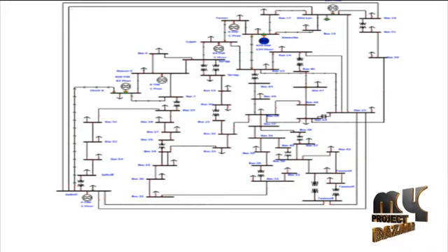receiving end voltages respectively. A small disturbance in the transmission system leads to instability when it is allowed to operate closer to its steady state limit. So a certain margin must be left in power transfer, and a small increase of electric power at the receiving end may increase mechanical power at the sending end, which increases the angle. For the angle above 90 degrees, the power transfer becomes less. This accelerates the generator and further increases the angle. This makes the system completely unstable.